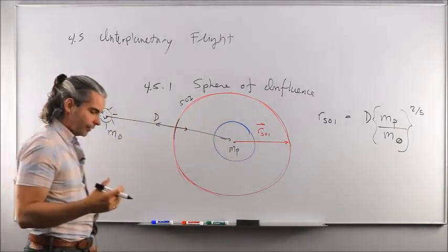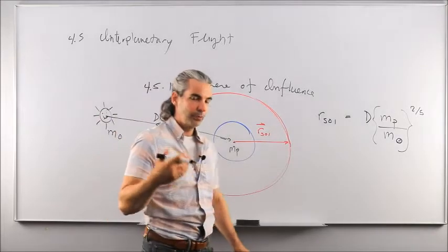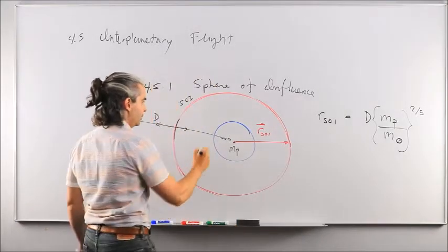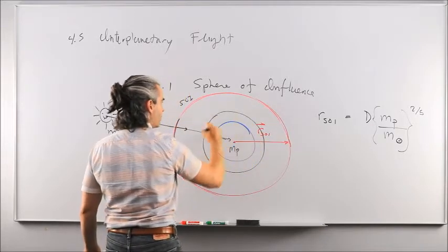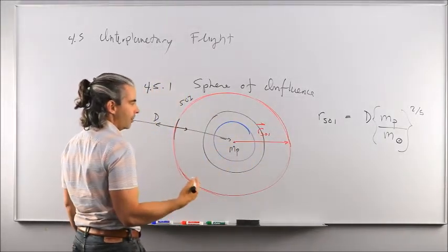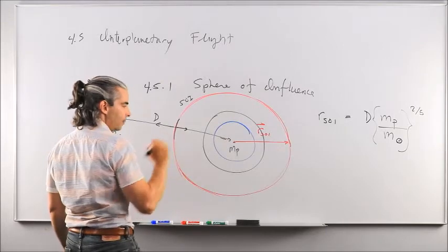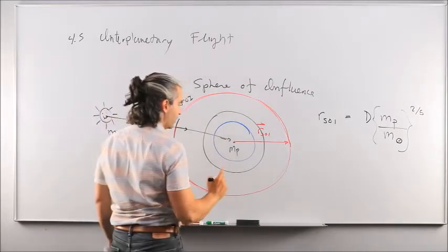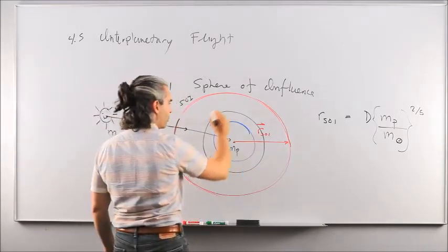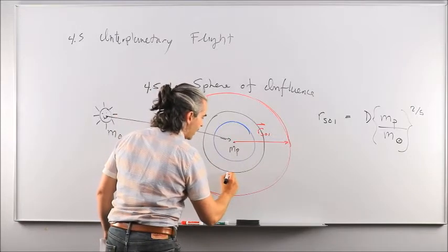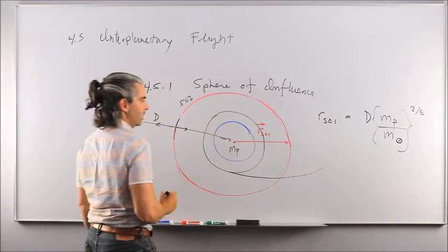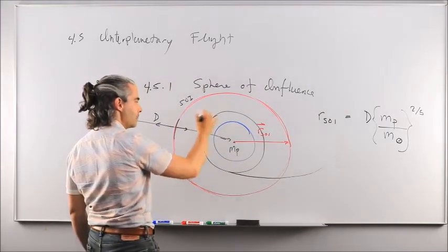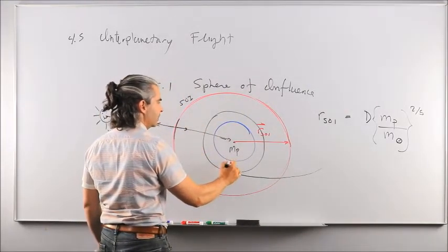So our objective to do an interplanetary flight will be to, again, start in a circular low Earth orbit, referred to as a parking orbit, and then apply a delta V maneuver to go from the circular orbit to a hyperbolic departure orbit, such that we will effectively escape the gravitational attraction of the Earth.